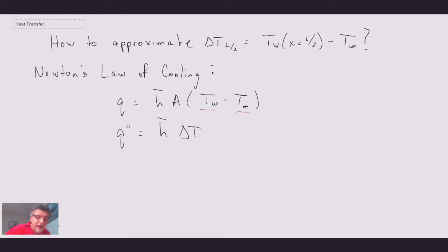And so we now have to resolve that because it will be a function of x. But from this, what I can do is write out that the convective heat transfer coefficient can be expressed as watts per square meter divided by our temperature differential delta T. So let's park that for a moment, and we'll come back and use this equation when we look at the next part. And the next part, remember I said that if you use the laminar relationship, so this is assuming that we would have laminar flow on our constant heat flux surface.